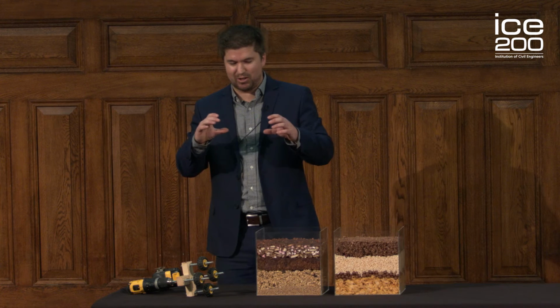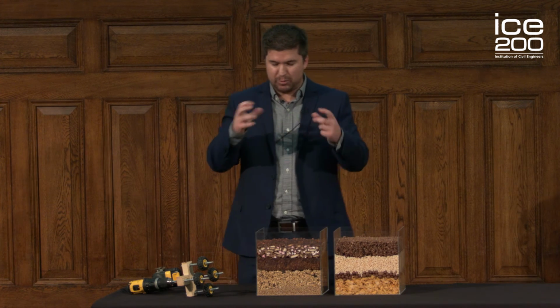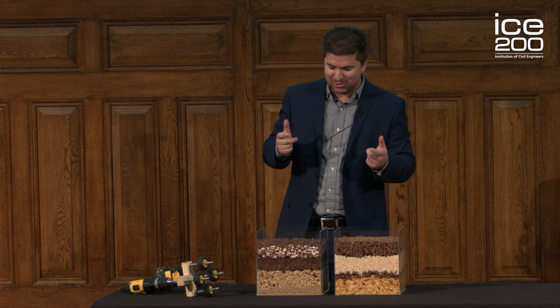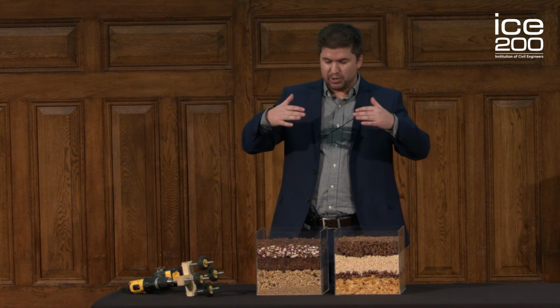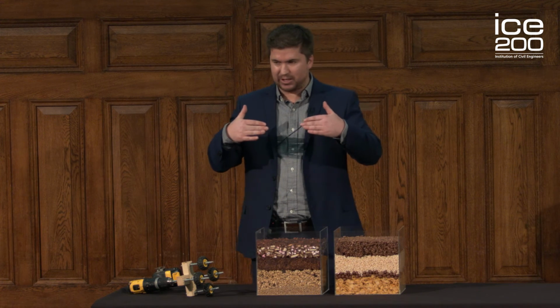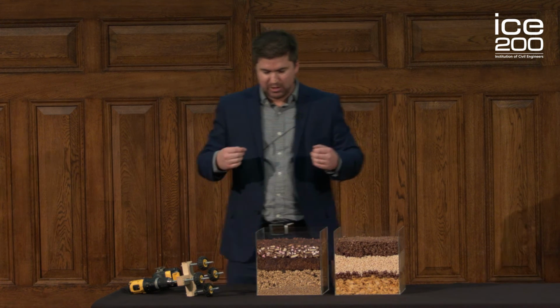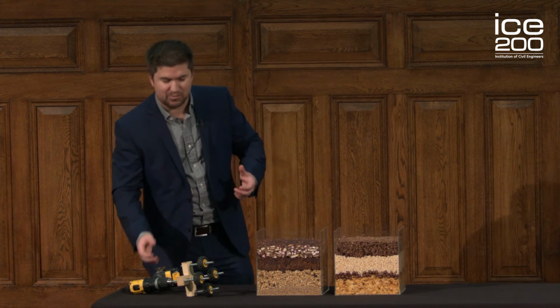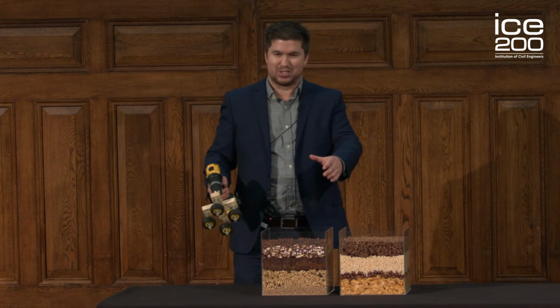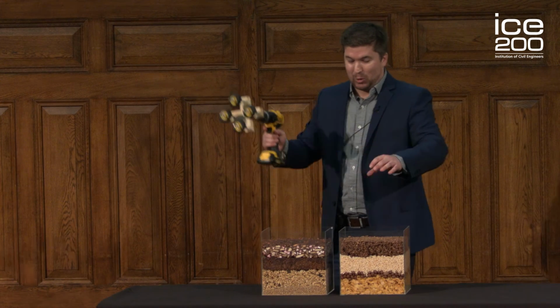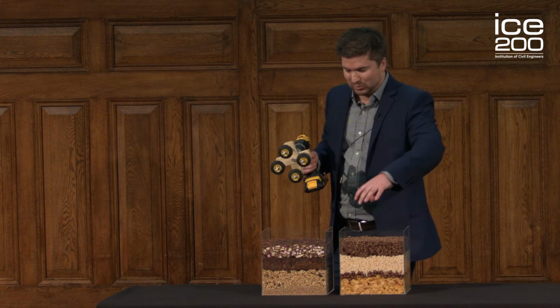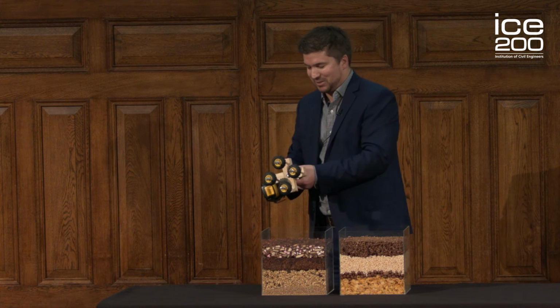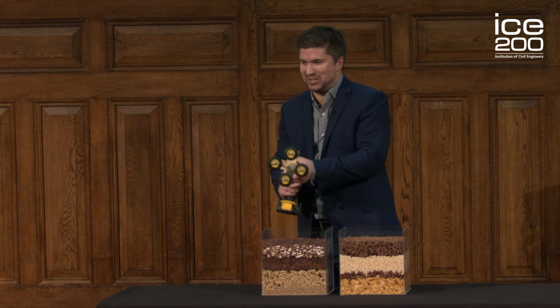What they represent are pieces of rubber, or polymer modifiers as we call them, and that gives the bituminous construction some flex so that it can flex under the load. And finally, it's all bound together by something called bitumen, represented by the chocolate. In the poor example, there's lots of voids, which means it's very brittle and is potentially going to collapse. And hopefully to demonstrate that now,